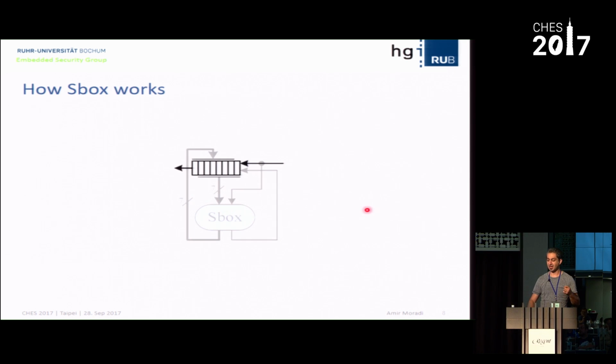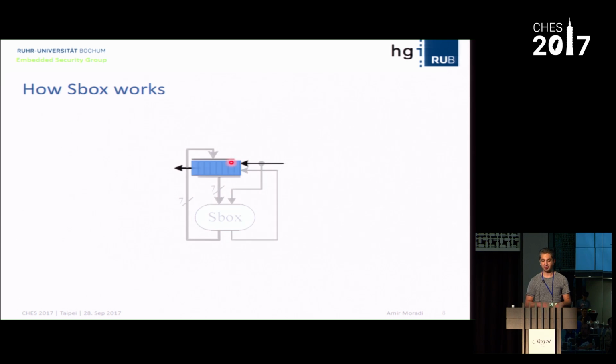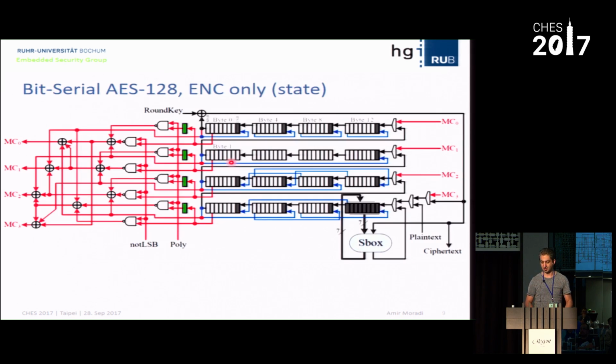First of all, how does the S-box serialization in parallel work? Suppose here you have the scan flip-flops. The input is shifted, in the case of the AES, 7 times, 7 clock cycles. Then in one clock cycle, when the input is available at the S-box, the input is not given to the scan flip-flop here, but the output of the S-box is given here. After 8 clock cycles, you have the full S-box in the design. Of course, this is a straightforward implementation of parallel: the input is just shifted 7 times, and then at the 8th clock cycle, the S-box output is realized.